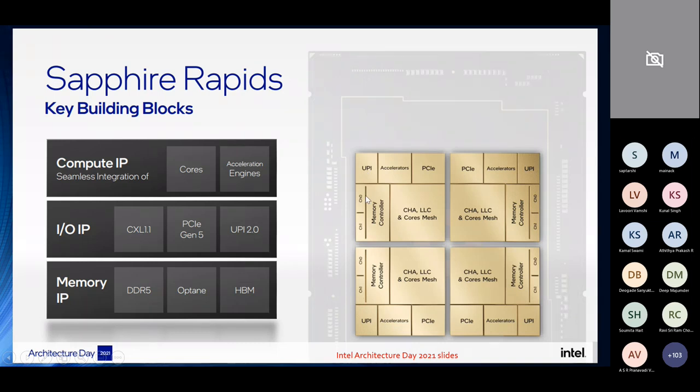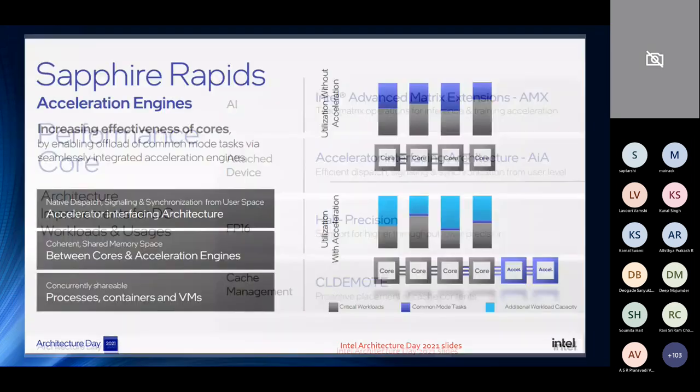So in this current generation of integration, what you can actually do is, instead of building this humongous die on one single wafer, you can fabricate these separately on maybe separate process nodes, depending on which one is more tuned towards a certain kind of architecture, and then integrate them back using this 3D stack Foveros platform, and get this system up and running, right? So I'm going to skip this.